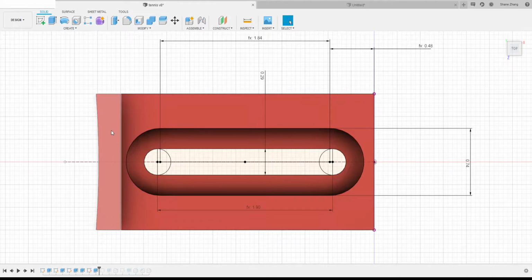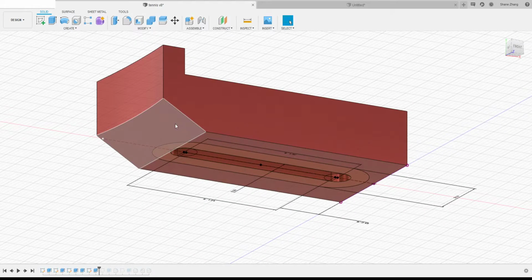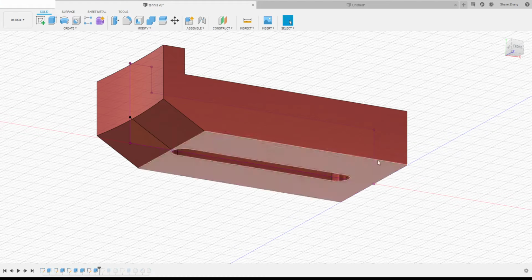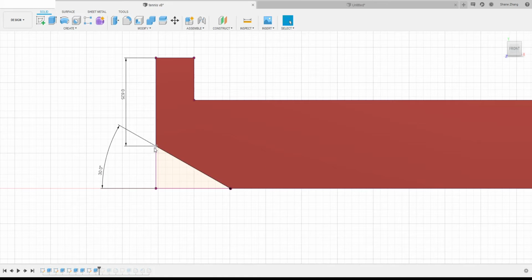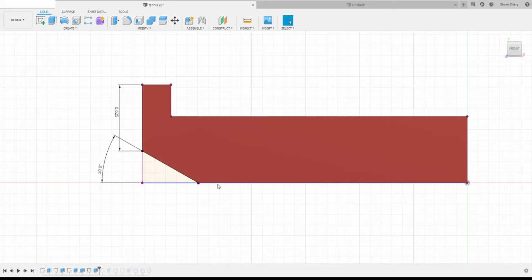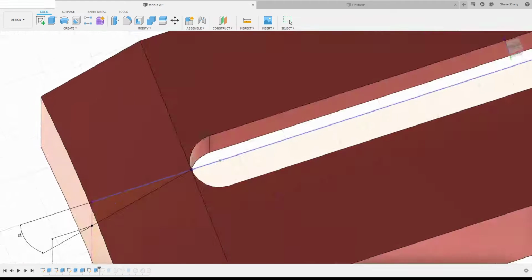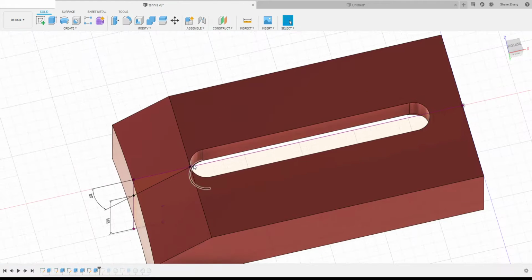And next is, okay, so next is this cut. This cut is, let's take a look at the sketch. Basically we're only cutting this triangle part off, and we'll take a look at the dimensions. Yeah, so I used the caliper to measure this distance, and this is just a guess. In reality I measured the bottom length, then rounded to 30 degrees. It was like 29 some degrees. And when you look at the actual piece, it matches pretty well to the slot.